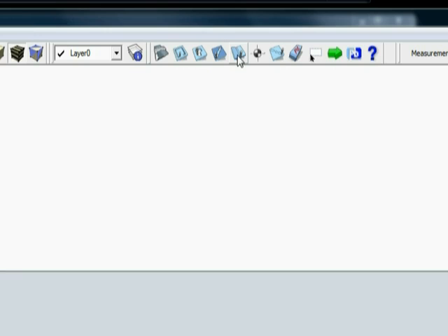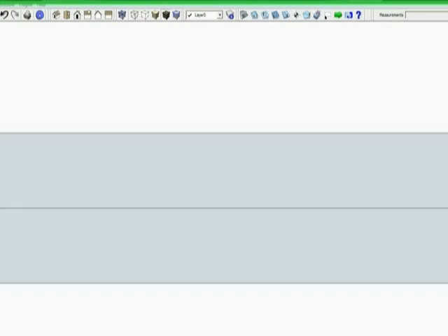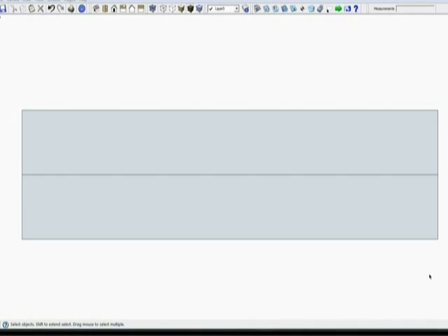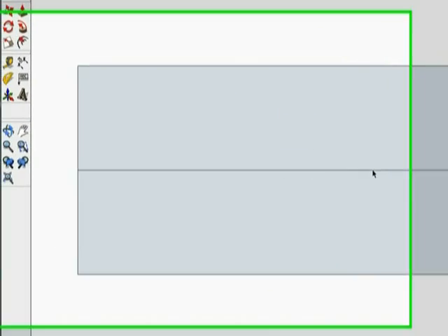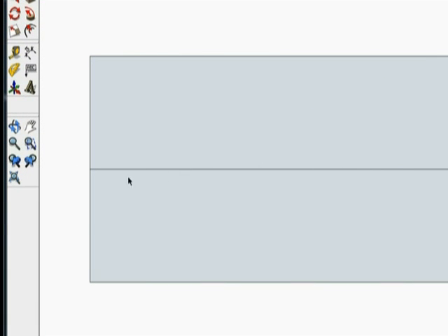Perhaps we've got something like you see here, just a long, rectangular strip of foam. That's what we're representing here. And maybe right down the center, we want to crease it easily to fold it back on itself, fold it back, I don't know, maybe 90 degrees. Well, to do this, we're going to use our fold tool to instruct our machine to come in on this line and then enter in at X depth, X being whatever we prescribe, and remove material all along the center line of this mid part of the sheet.